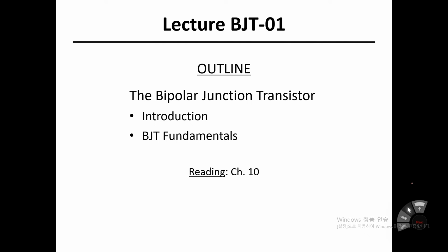So basically, we have used two different regions. For example, in the case of the PN junction diode, we have used P-type and N-type silicon semiconductor materials. How about the MS junction? Metal and semiconductor. Whatever the type is, N-type or P-type, anyhow, it is semiconductor. So we can say that metal and semiconductor, those two different materials, have been combined to build up the Schottky diode or ohmic junction.